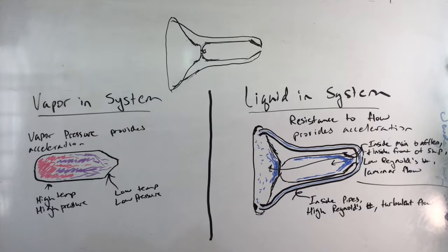And this flow isn't completely unobstructed. Remember, there are those paddle-like extensions for the baffling because they have to go through. But still, the liquid in this part of the system is basically going through one giant pipe and at a relatively low velocity and pressure. Compare that to the liquid going back to the front of the ship in the return circuit tubes. Remember how I discussed the different flows' Reynolds numbers when I was describing the shape of the baffling?